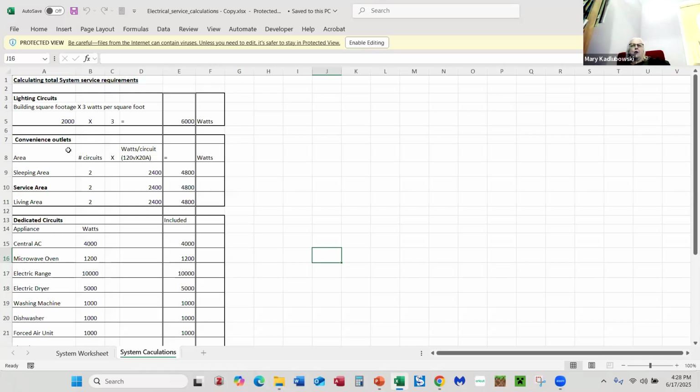So generally you don't want one circuit breaker to do the whole room. You want to split them between rooms so that if a circuit breaker pops, you still have power in that room. So you would do like one circuit would cover half of each of the offices. Should I also make the breakers and the wire rated for 20 amps instead of 15? Or what do you think? Definitely. Yes. Okay. All right. Sorry for interrupting.